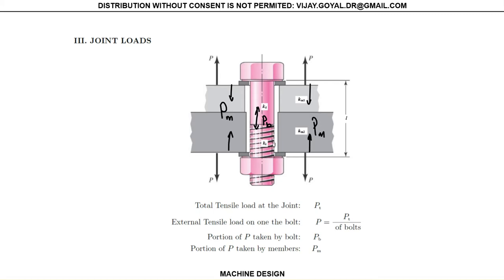So when you're solving these problems, you want to make sure this is always engaged. You want this to be always touching. You don't want this to be loose. So immediately you can see that this can never be bigger than zero. And if it's just barely equal to zero, that's the moment where they're barely touching each other, but there is no preload applied to the problem then.